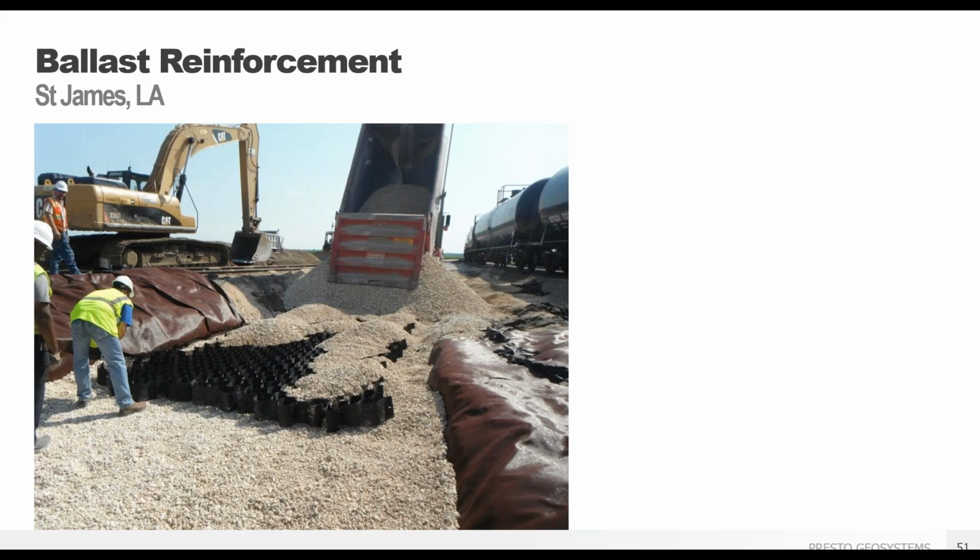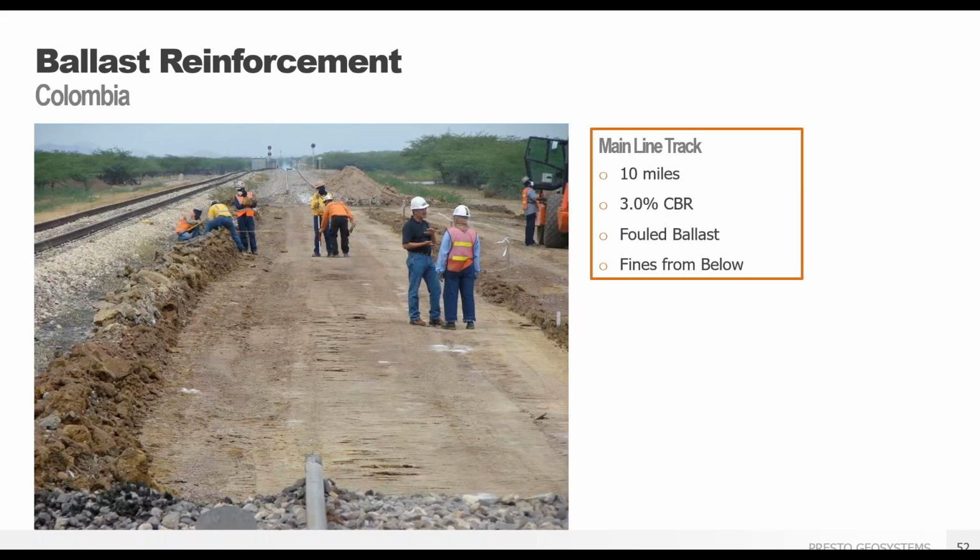So here you can see a closer picture of how we're spreading out the GeoWeb and backfilling it with that aggregate. And then once again we'll just burrito wrap that right over the top of the GeoWeb so you don't push that 12-inch base out into the poor subgrade.